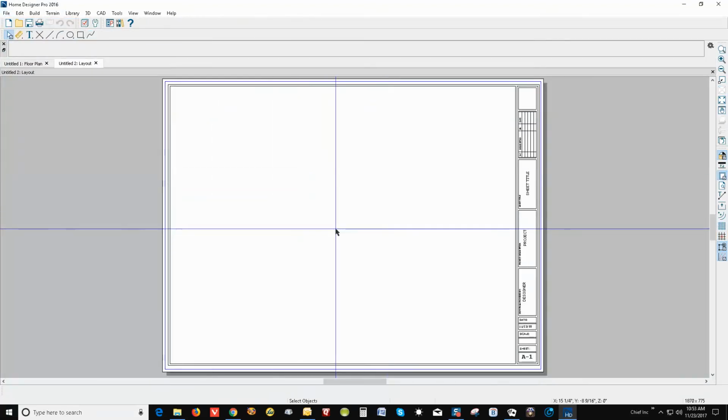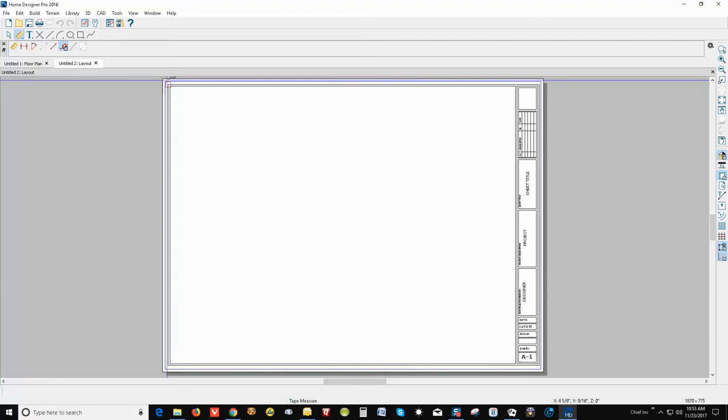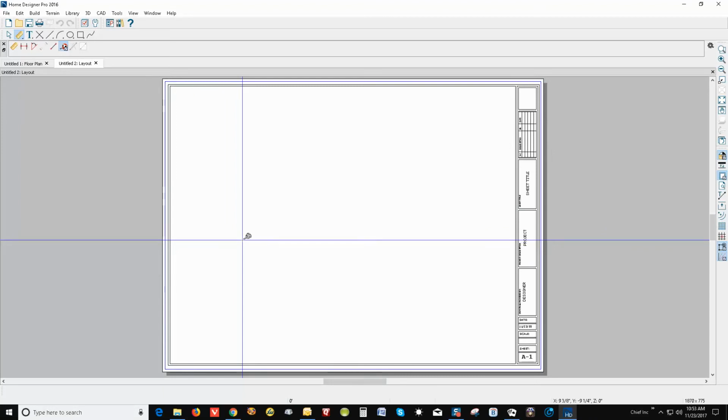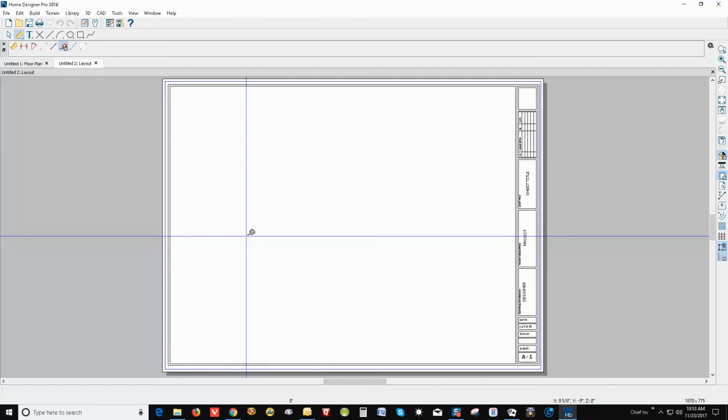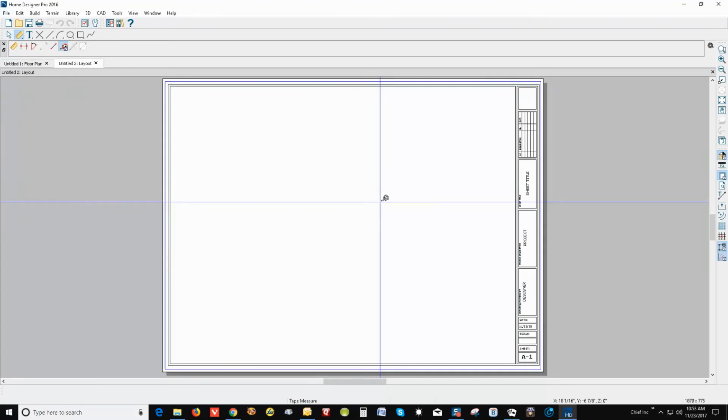And it gives you a virtual blank piece of paper. And I recommend that you get to the Dimension tool and verify its size. And don't assume that you know what the size is. That's 18 by 24. So this is the largest size that Pro can create, 18 by 24. If you want something smaller, you're going to have to make it yourself.